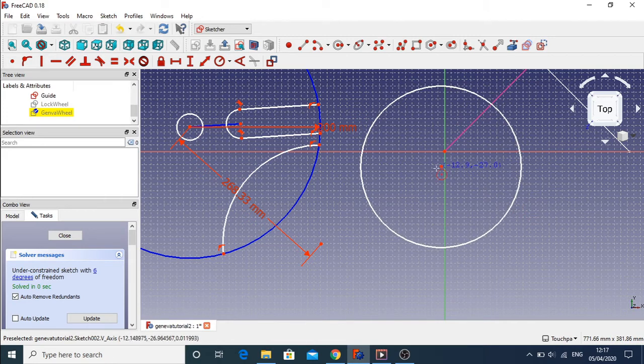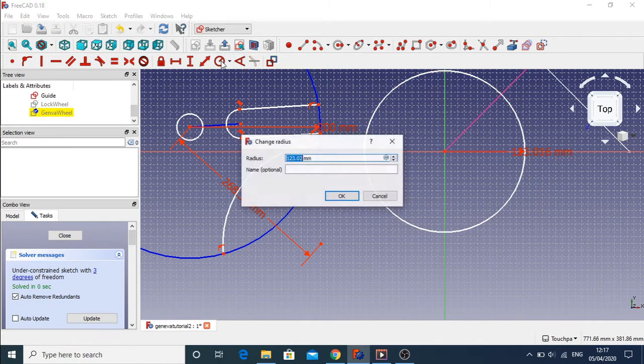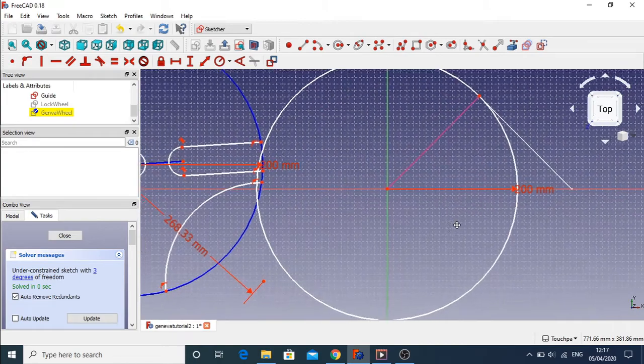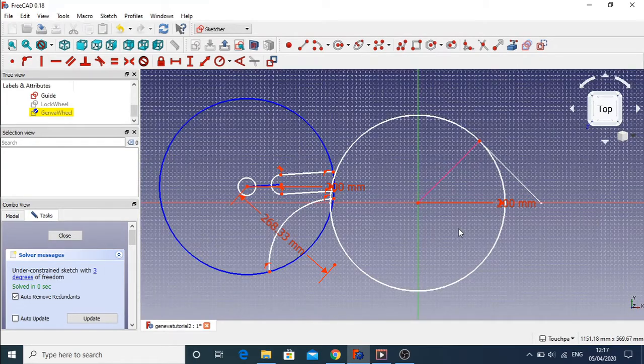Create a wheel, I'm going to anchor it into the XYZ origin, or the axis of our sketch, and I'm going to set the diameter 200mm. So that's all good. So we've got that all set. Holding down Shift, I can move this page about. So let's center that bit and zoom out.